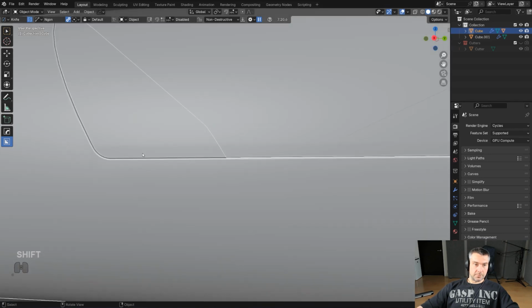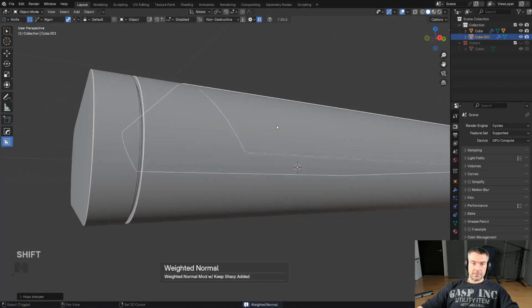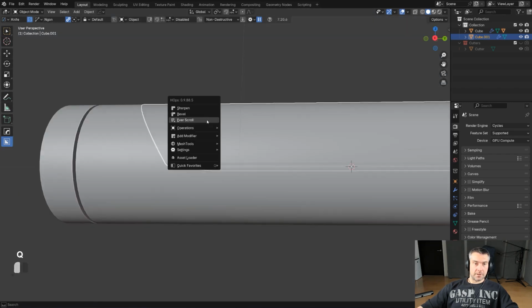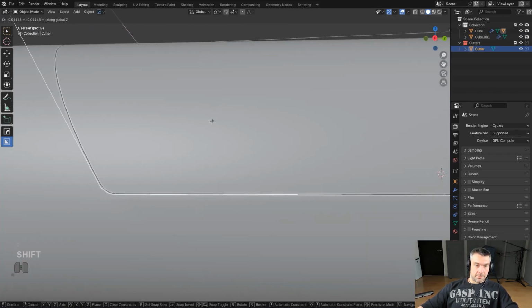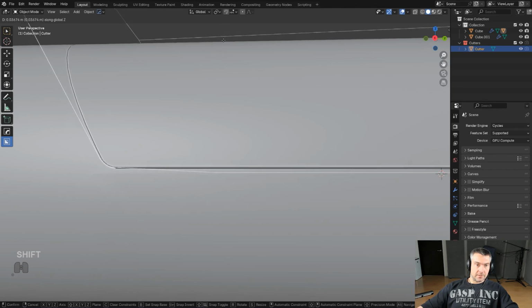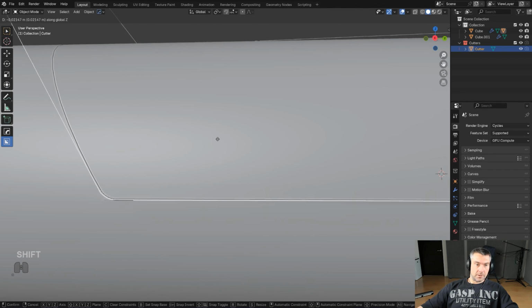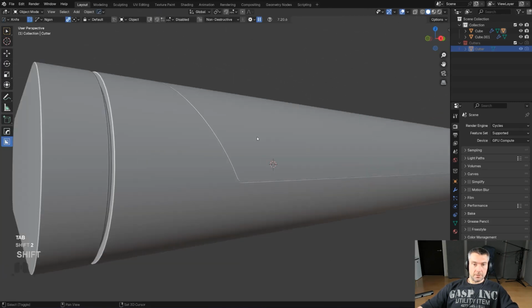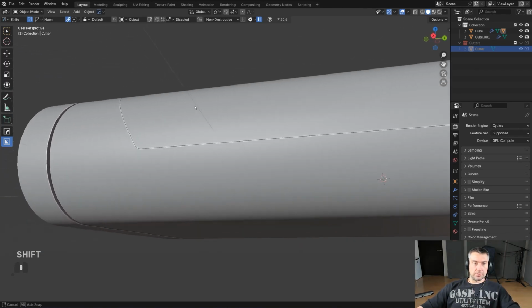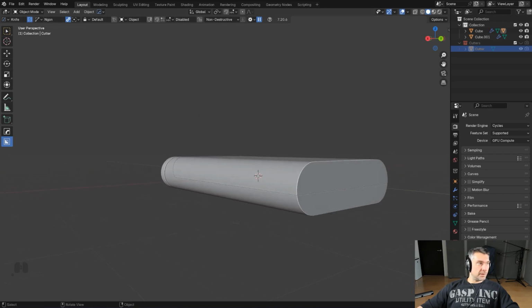This one on the bottom, there's a little bit of a shading problem, but let's introduce weighted normals. This didn't fix my problems. Let me just recall this cutter, grab it, and let's just try to move it up and down to negate this shading problem. Maybe we need to run it really close to the edge and remove one of these edges. This is acceptable, I think. That's better. See, sometimes you need to nudge your cutter to a position to fix the shading problem, okay?